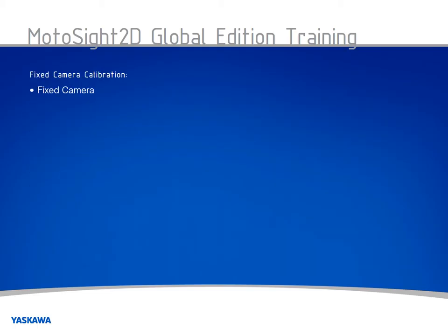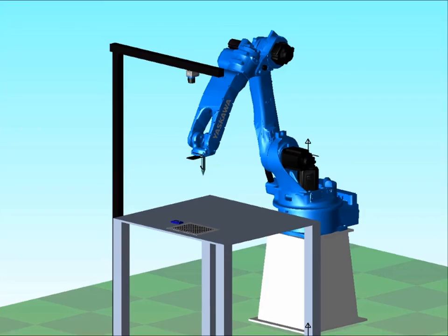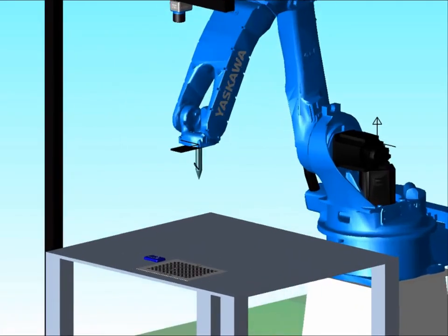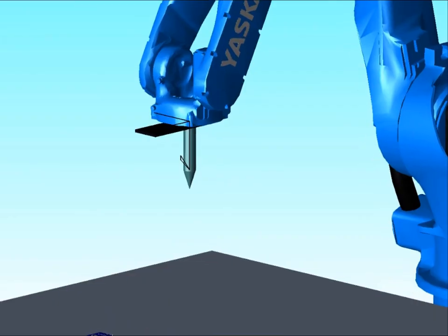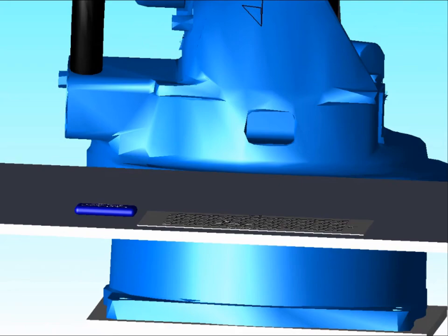Now, let's get started with fixed camera calibration. Please note that this step is required even if you have a mobile camera setup. The first thing we need is to create what I'm going to call a pointer TCP. The pointer TCP should be somewhere in your end of arm tool, so you can physically see where the robot controller is calculating the manipulator position. We will use the pointer TCP to teach the user frame to coincide with the calibrated camera frame.